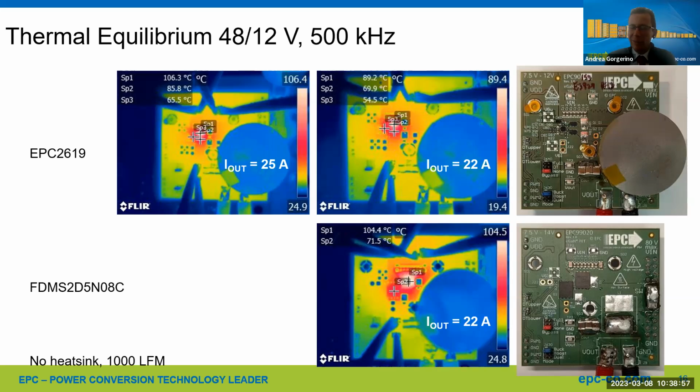question. I don't have the charts here, but the way I interpret optimal switching frequency, and it's true for any semiconductor technology, is that you always have a trade-off between conduction and switching losses. If you go to a very low switching frequency, you're dominated by conduction losses. If you increase the switching frequency, you're dominated by switching losses. Naturally, there's a minimum in that.